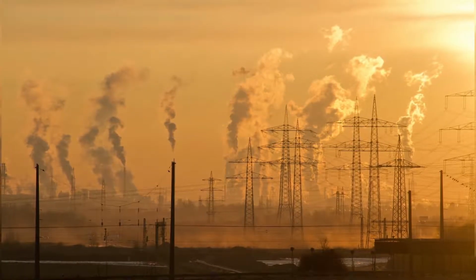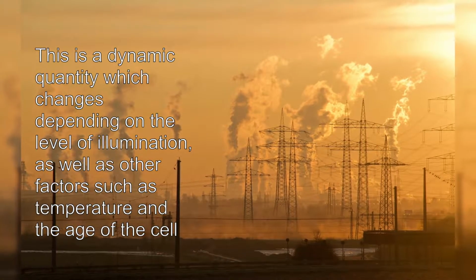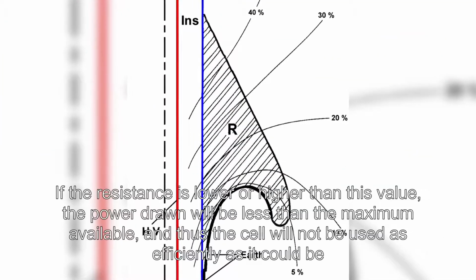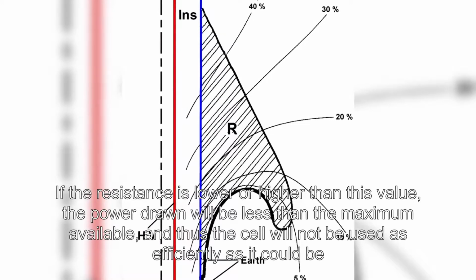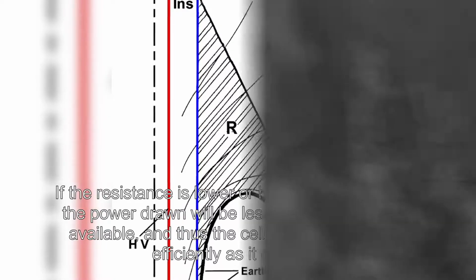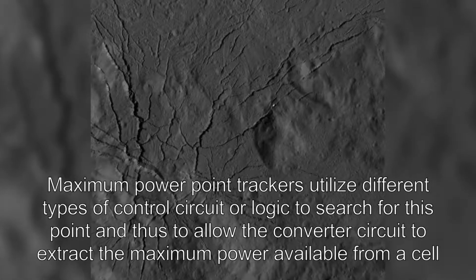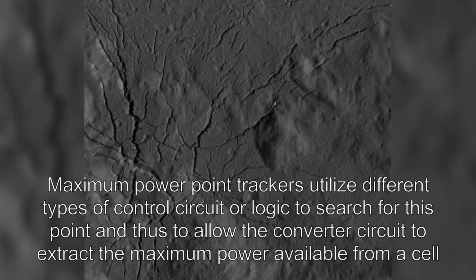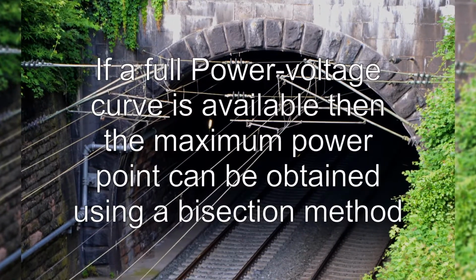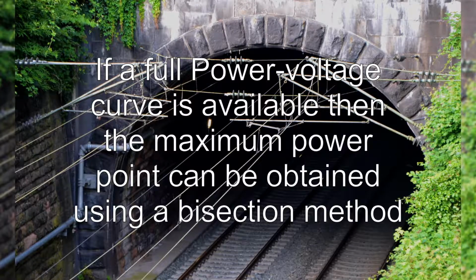From basic circuit theory, the power delivered from or to a device is optimized where the derivative dI/dV of the IV curve is equal and opposite the I/V ratio. This is known as the maximum power point and corresponds to the knee of the curve. A load with resistance R = V/I equal to the reciprocal of this value draws the maximum power from the device. This is sometimes called the characteristic resistance of the cell. This is a dynamic quantity which changes depending on the level of illumination, as well as other factors such as temperature and the age of the cell.